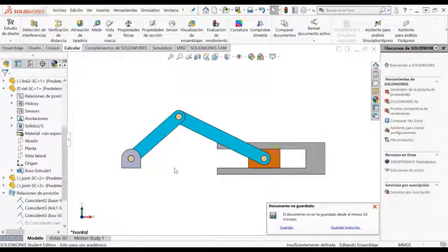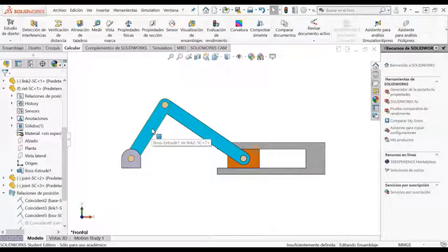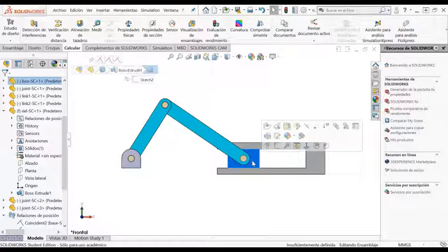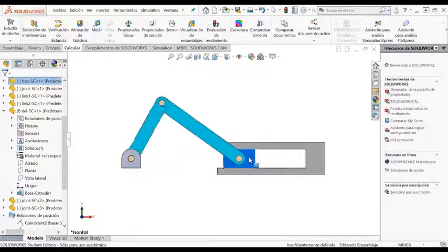Okay, so I want you to think of that because it gives us some general idea of how things are in the real world. So let me say that again. In SolidWorks, this one moves. I can say that this is my input, but there are some applications like the motor of a car in which that guy is the input. And you can simulate that in SolidWorks. You can say, okay, I'm going to add a linear motor to this element so that it moves this way. You see, here I'm controlling the slider and still be able to move the entire mechanism.